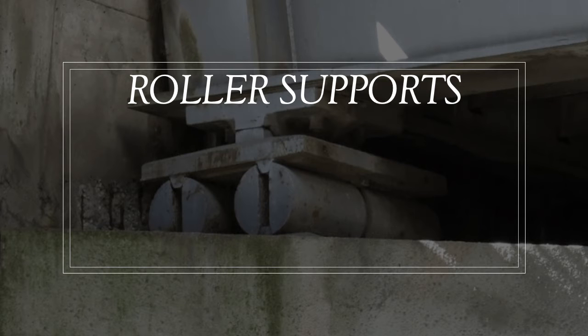Roller supports. As horizontal force is applied to bridges, the roller support will move across the surface without resisting the applied horizontal force. Roller supports are unable to provide resistance to lateral forces, which is an issue as most structures are subjected to lateral loads.